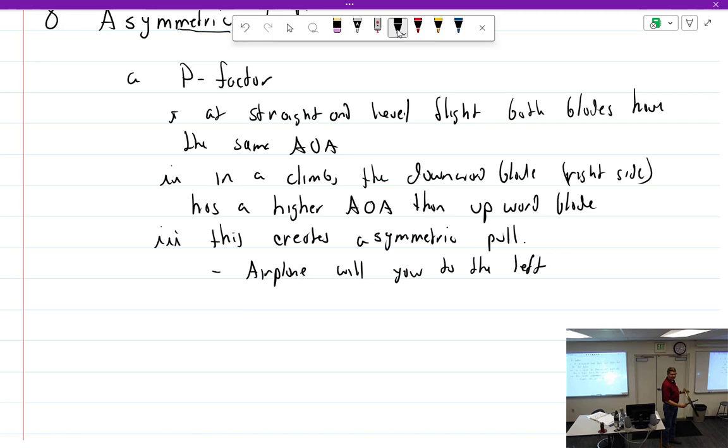I didn't make it go that way. Right, that is true. As soon as I stuck it in, it's like, whoa. It's off to the races. So I'm just gonna lift up on this end and try and straighten it out. Ready? You can see I'm just holding it right there. It's going that way because I'm trying to push this down. So in a tail-wheeled airplane, when you take off and you bring the tail up, it goes hard left.